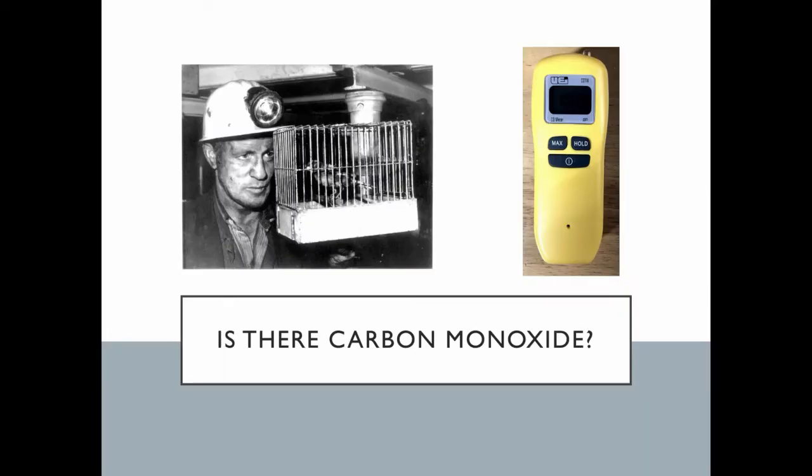The other thing I like to do is make sure that I'm safe. In the old days, coal miners used to use a canary in the coal mines, and if the canary stopped singing, you took off and ran because it was carbon monoxide. Well, customers today wouldn't allow you to bring a canary into their building, so I use the next best thing. I use a personal carbon monoxide detector, and I keep it clipped to my belt just to make sure it's safe when I walk inside a boiler room.